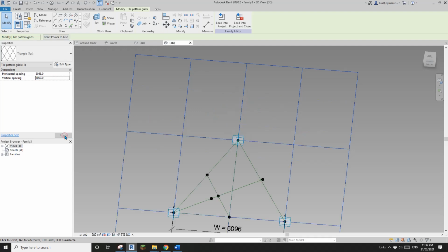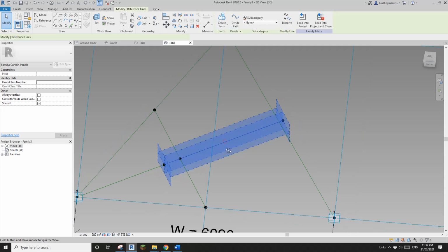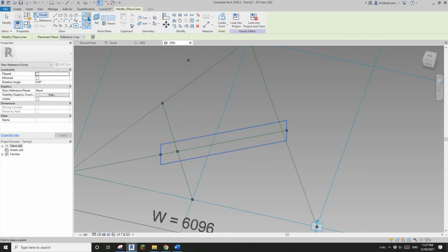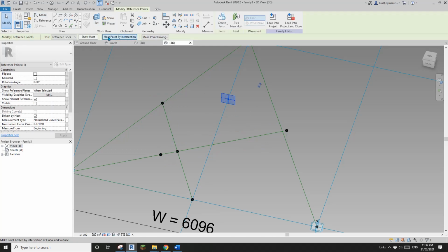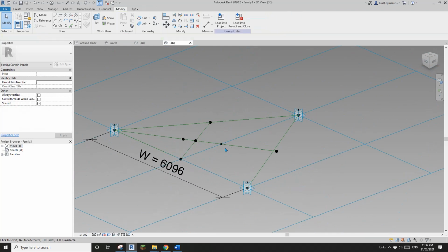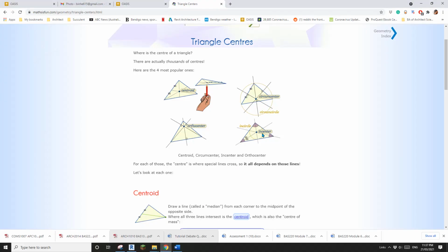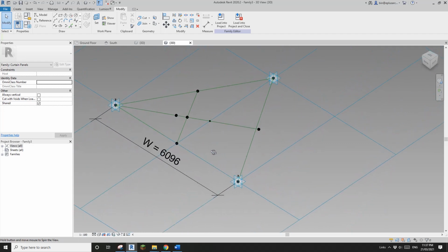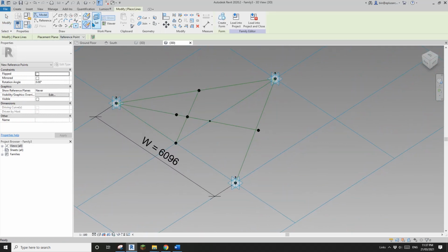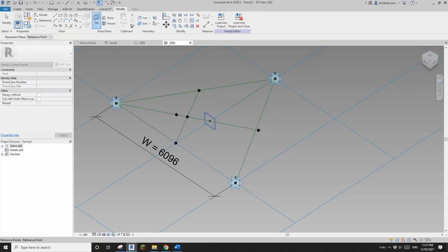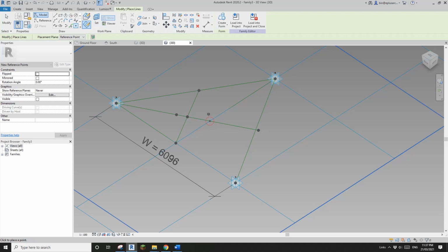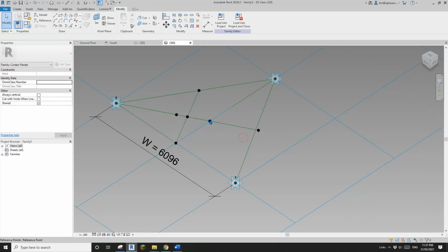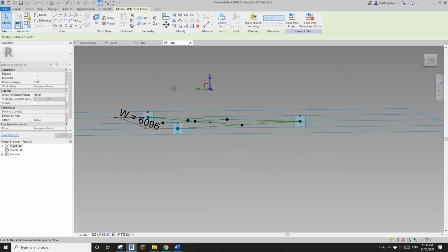5 meter, still aligned. Now if I place a point, draw on face, place it on this reference line, select this point, use host point by intersection, and pick this reference line. So now we get this. This is the incenter. Okay. So the next is we need to place a point, draw on work plane, and pick the horizontal work plane of this point and place it on this point. So now we get this.